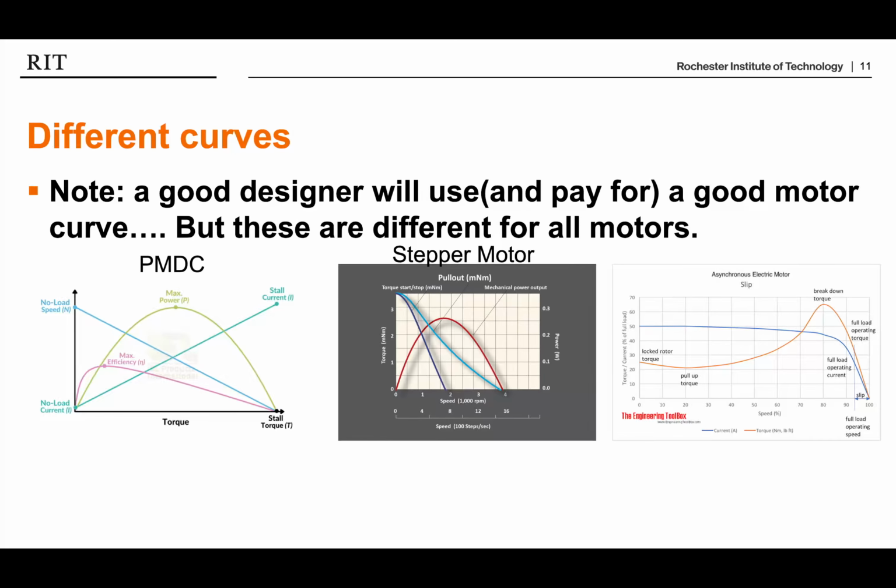So again, if you think about it, we have the center part of the motor that's rotating, just like any other rotating part, that has inertia, which means there has to be some torque to get the rotor moving, and we also have to be able to stop that, and stopping a rotating thing requires torque. So this shows us the torque to start or stop a motor at any given speed, for this specific stepper motor.